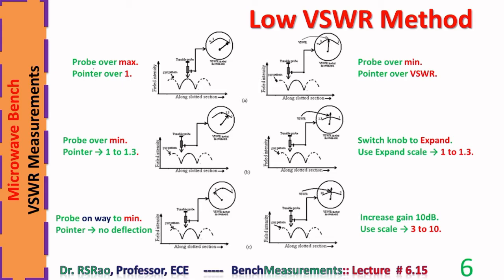Starting point: the probe is over maximum, the pointer is over 1. Then move the probe over to a minimum. Now the pointer moves leftwards, or in the anti-clockwise direction. The reading the pointer gives is VSWR. This is the basic, or fundamental, step. If this VSWR happens to be between 1 and 1.3, then to get the accurate, exact value of VSWR, we use the expand scale. Now place the probe over minimum.